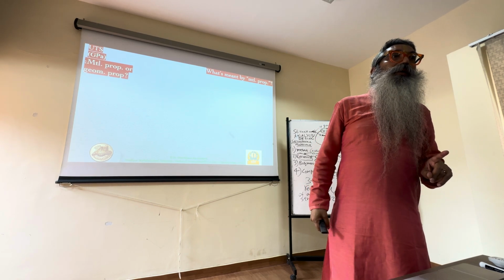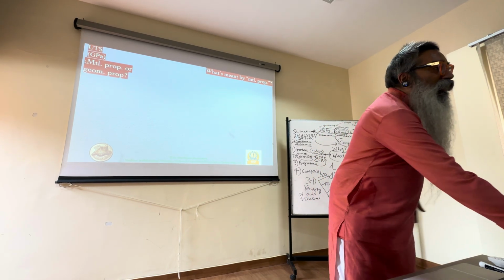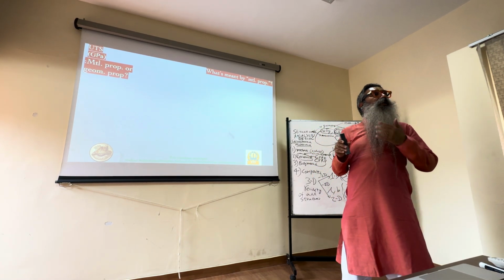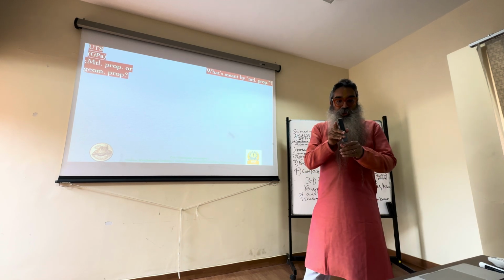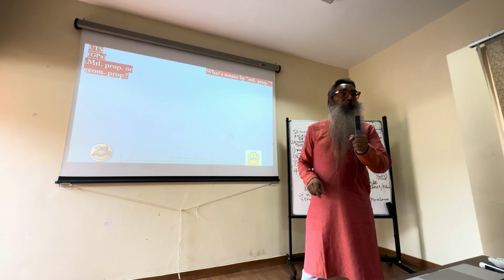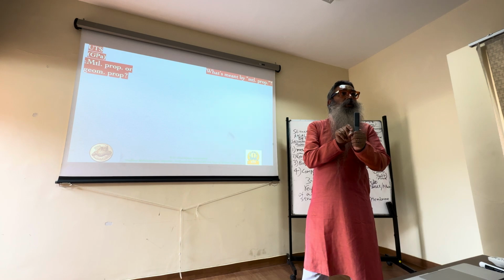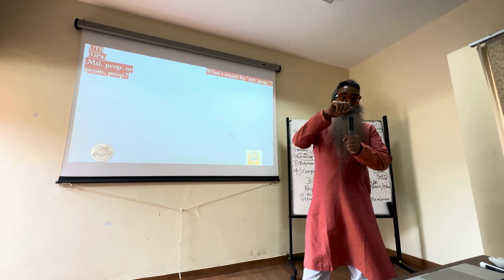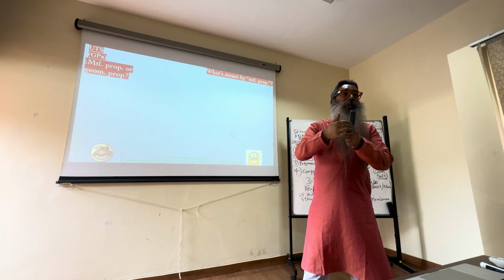Stress as well. Yeah, so remember, how do you get to sigma u? You take a uniaxial testing machine, UTM, in which you fix one end of the specimen. The specimen itself is made to a particular dog bone shape, according to certain standards, ASTM standards. Then you start pulling the other end, and you put strain gauges on it.